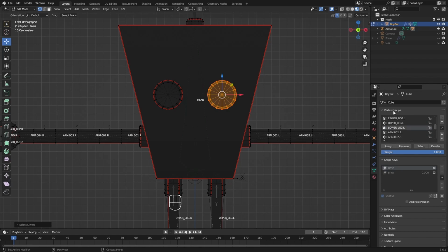So here in this Vertex Groups tab, I'm going to click on the plus button and then change the name of this guy here to left underscore eye. Enter. And I'm going to make sure the weight is 1 and I'm going to press assign.